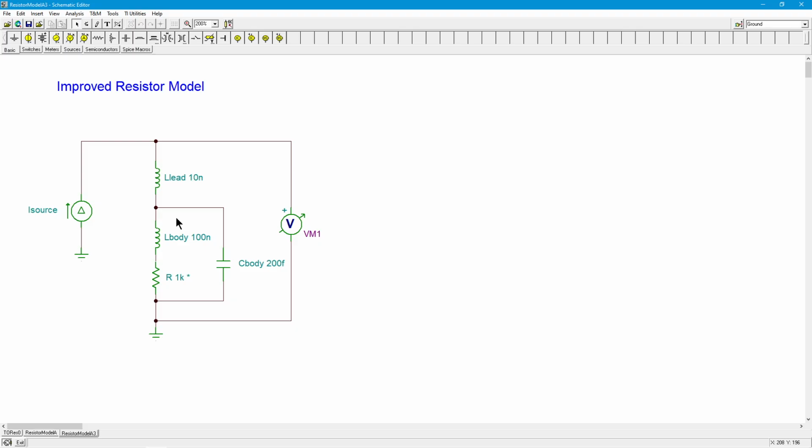I'll tell you right up front, resistors that are in the hundreds of ohms, like a 400 ohm, 500 ohm, 1000 ohm resistor, tend to have the most extended frequency response at the high end. When you get particularly large or particularly small resistors, tens of ohms, single ohms, hundreds of Ks, things like that, you start to see the frequency response limitations earlier, at lower frequencies. Okay, so we're going to run through a whole bunch of different values of R given these inductive and capacitive values.